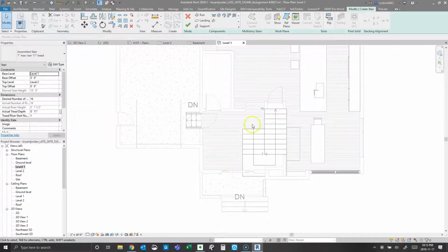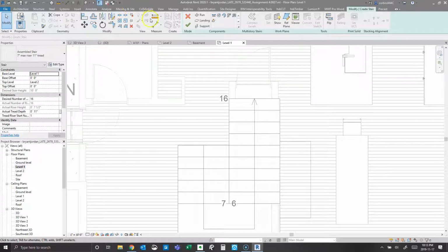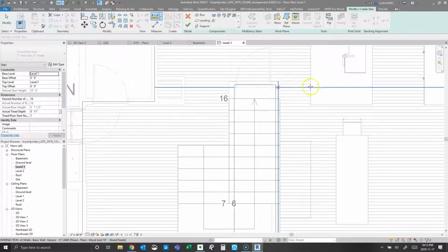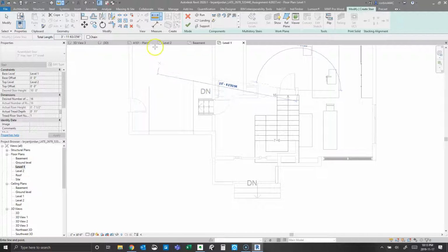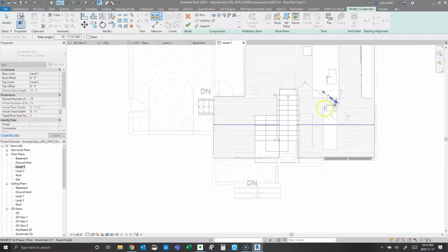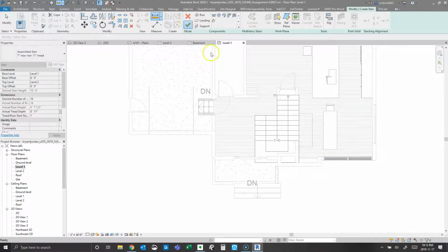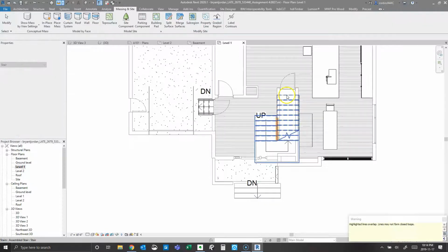Something like that. So based on this stair move, proportionally there's some stuff that needs to be fixed up in here. You can also tell that this dimension between here, you really want to have 3 feet minimum for like a private space, so like a bedroom, but really you want to have 4 feet wherever you can. So I'd recommend doing some tweaking to this to figure out, I guess, better proportions for things.